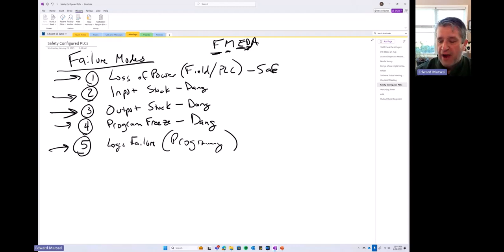So for instance, if you have a stack overflow diagnostic in your PLC, then you need to write your own code that says if the stack overflow flag is set to true, I want to de-energize that output that is going to the master trip relay to de-energize all of the power going out to the field. So this last item is an exercise of going through all the error codes and writing a big logic gate that says if these error codes exist, de-energize all my power going out to the field. And that's how you do that.